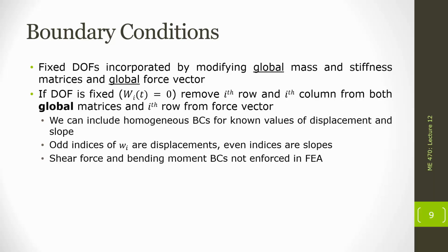In the axial problems, we only were doing this when we had zero displacement boundary conditions and didn't worry about when we had zero strain. Similarly, for these transverse problems, we're only going to eliminate the rows and the columns for the degrees of freedom that have zero vertical displacement or the rows and columns for zero slope.